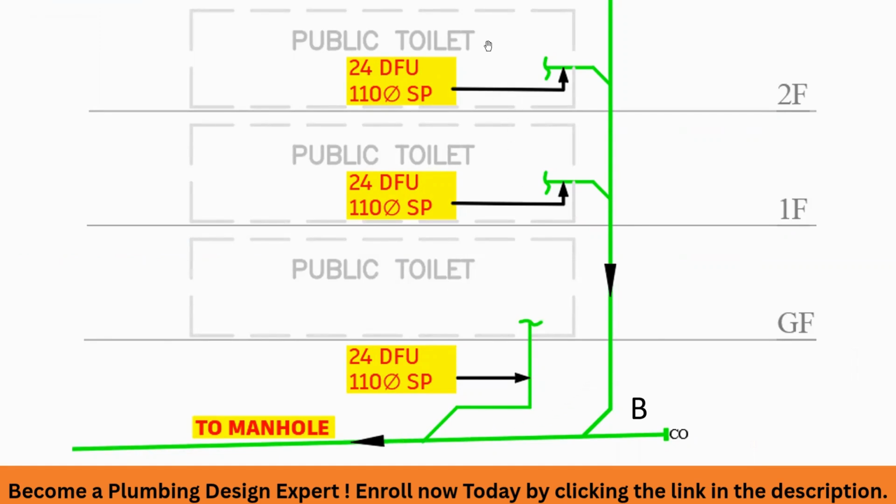Why? Because as per the standard, to maintain a uniform flow in the stack at this lower level, the minimum straight pipe distance has to be 2.5 meter. Before entering the building drain, the pipe has to run without any discharge for a distance of 2.5 meter.